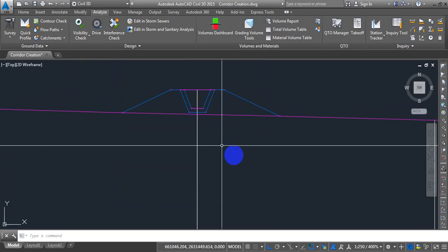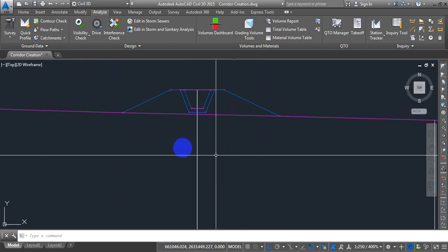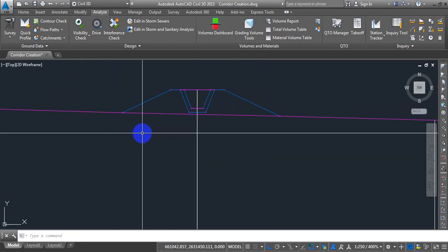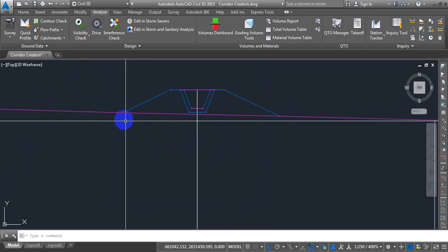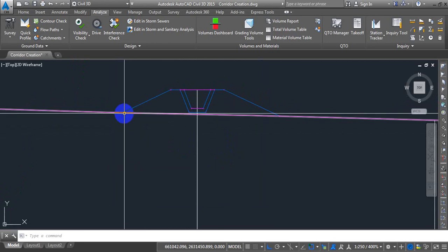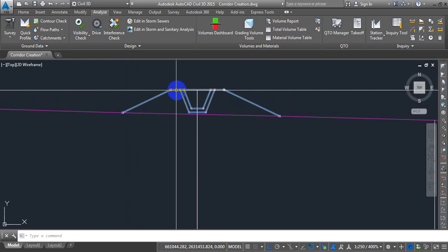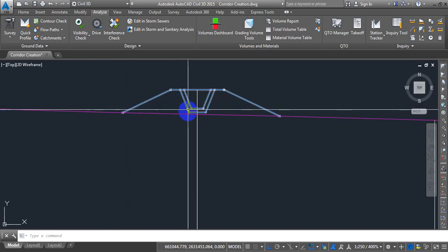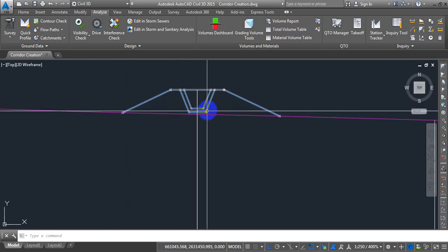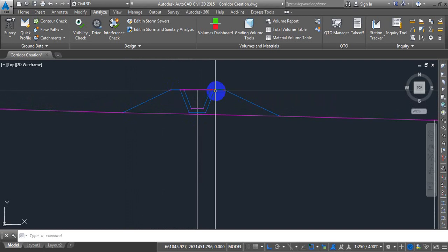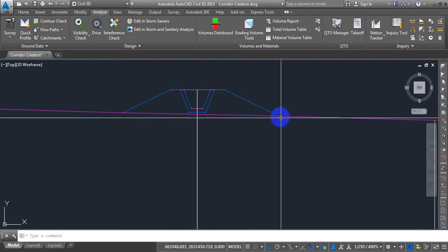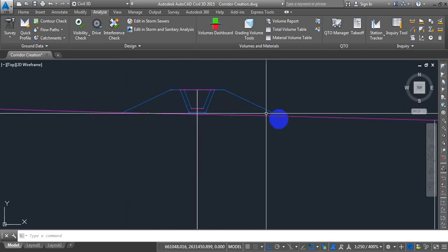Okay, what I have to do is that I need to define a new surface for myself, both for cut and fill. In case of fill, I need to introduce a new surface, which will be starting from here, going along this link, and then going along the berm, and then along the channel edges, coming this way, and then berm, and then slope along the slope.